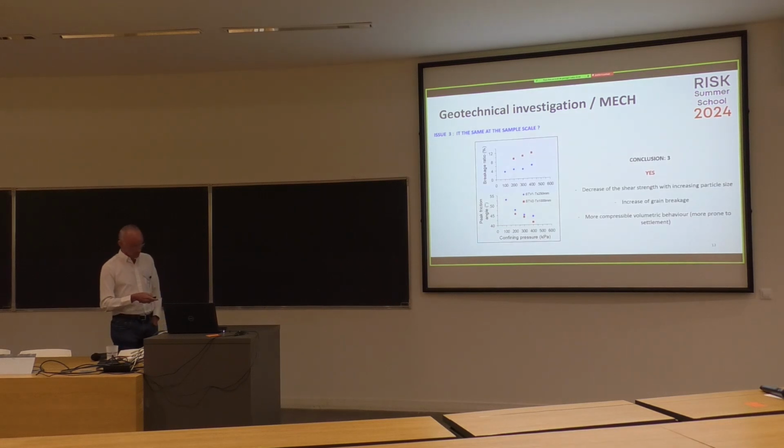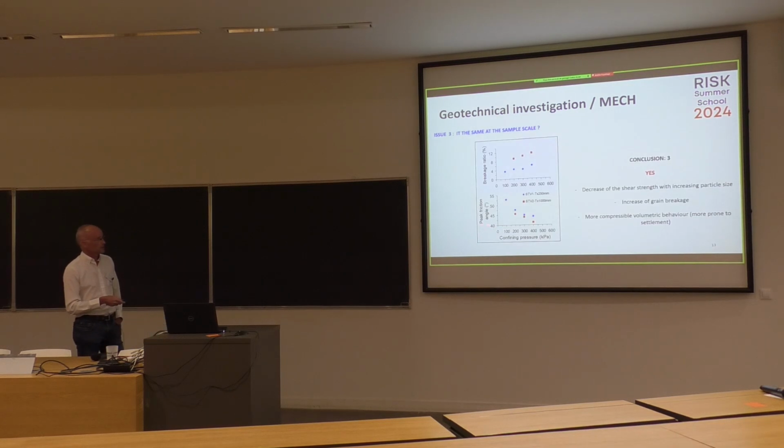So what is important first is to observe this curve. I just put the results from the intermediate cell, in blue, and the largest cell, in red. An indicator of the strength of the resistance is what we call the friction angle from the Mohr-Coulomb failure criterion.